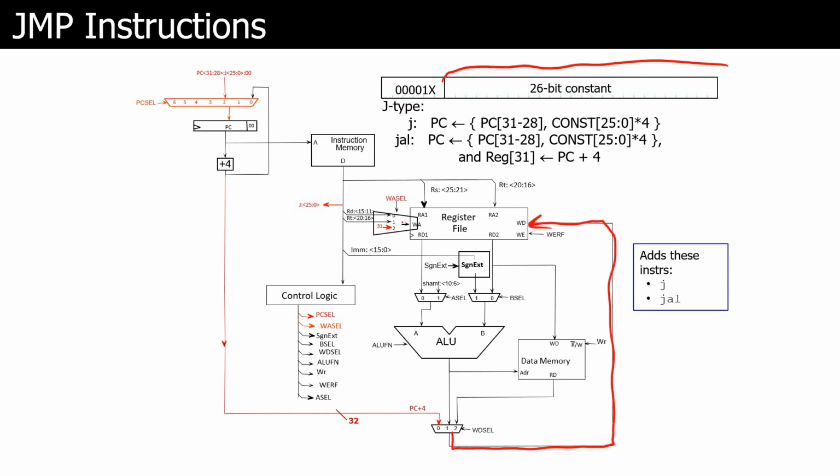And then for your write address, we have renamed what was previously just the same thing as BSEL to write address select. So it lets us select between the RD register, the RT register, and register 31, which is RA. So if we're doing a jump and link, you're going to have 2 for our write address select value that's sent into the multiplexer control bit, and that lets us write the address to register 31, which is the RA address, and that lets us return.